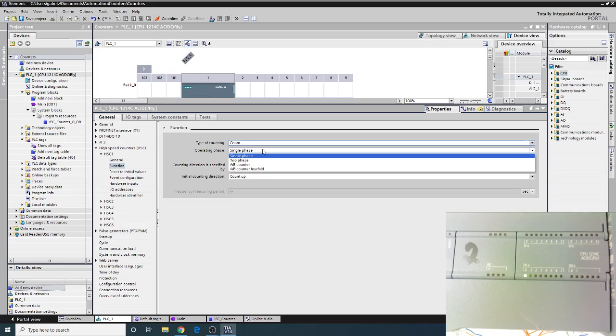So you can always figure out which phase you're in, and then you can always see whether it went 1 click right or 1 click left. So it is actually able to determine which direction the motor is spinning, so that it knows whether to count up or count down based on that. In fact, the robotic arms up top over there have encoders in them. If we want to use those correctly, we have to enable these high-speed counters to use those encoders, because they go so quick the program itself can't keep up with it.